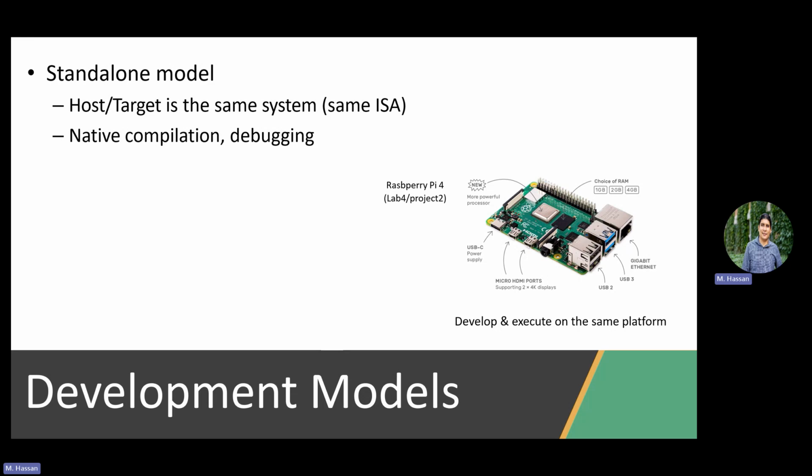Programs really need to be optimized. I cannot have millions of lines of code in an embedded system. Excellent. To do the same task, but with much fewer lines of code. And the reason for this is memory space. Embedded systems are usually resource constrained, compared to your laptop, for example. So you have to be aware of the resources, and we will see some of the implications, how you pick your data types, how you define your memory behavior. That's one of the things to keep in mind, which is the most important one, by the way.